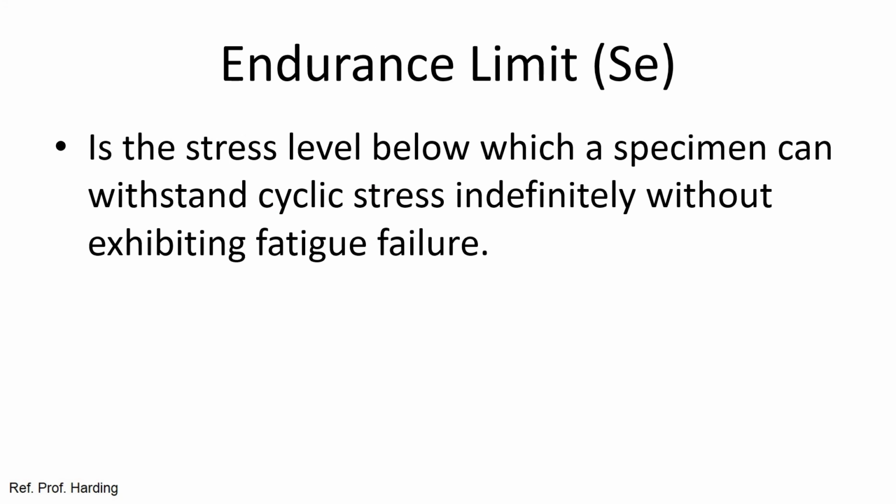When it comes to implant fracture or implant component fracture, a very important concept to understand from engineering is endurance limit. So what is the endurance limit? Well, it's the stress level below which a specimen can withstand cyclic stress indefinitely without exhibiting fatigue fracture. So what are we looking at?